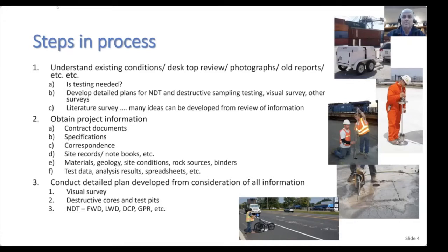Literature survey. Go and consult the literature. Many ideas can be developed from a review of information. Obtain the project information, contract documents, specifications, correspondence, site records, etc., and include geology, site condition, rock sources, etc. Test data analysis, spreadsheets, a lot of data to look at. Whether we need to consider in our detailed plan development, things like visual surveys, destructive cores.